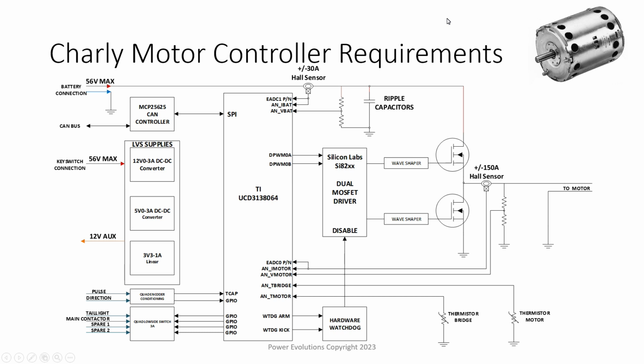So now that we've got the limits set for what we need for the controller, and we have our requirements in place, I've sketched together a block diagram of what I'm going to try and build. So what we have then is a half bridge power PWM bridge. The wave shapers are just RCs, well, actually there'll be more R's and a D, which will allow you to do an asymmetrical wave shape.